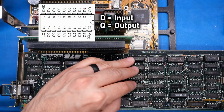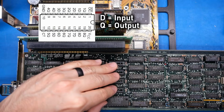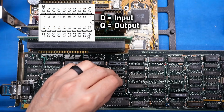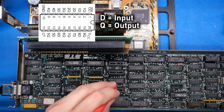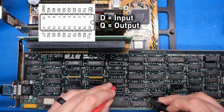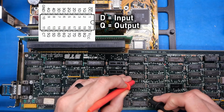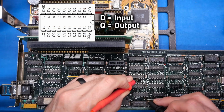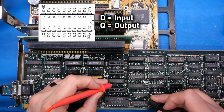So data line 3 on these chips, that's bit 2, is making its way to the inputs of these two chips. These chips right here might be going to those chips. So what we can do is just pop one of these in here, and I'm just kind of curious now. So let's look at that one there, and let's see if these make their way to these chips. There we go. It's right there. Yeah, same exact pin. I'm pretty sure that... Oh. Oh, look. It goes there too. So in my running the multimeter over here, I didn't do a good enough job. So these are actually parallel.